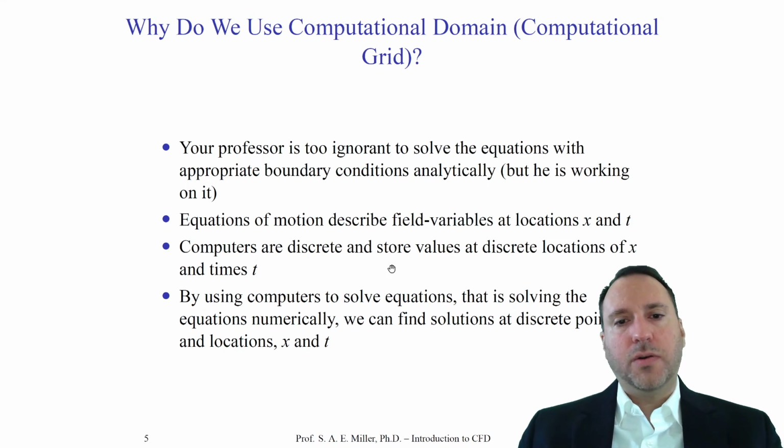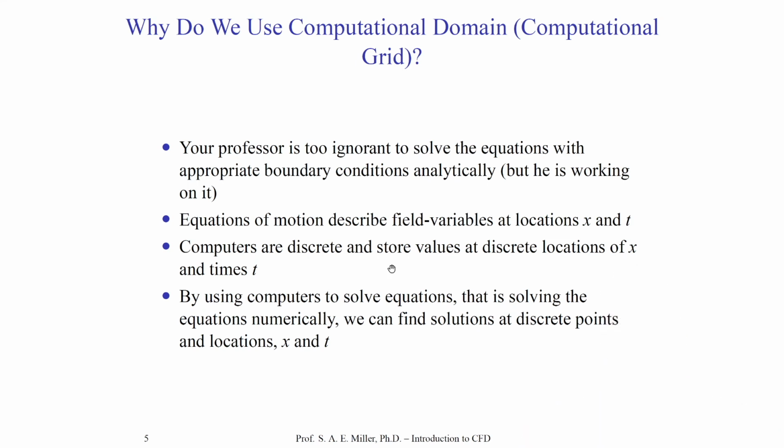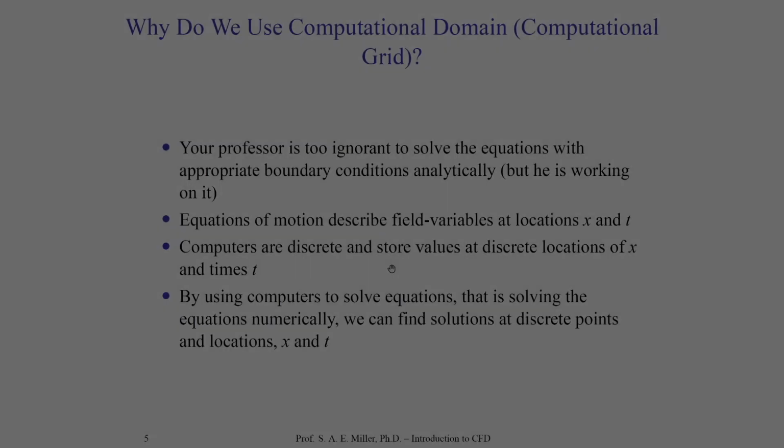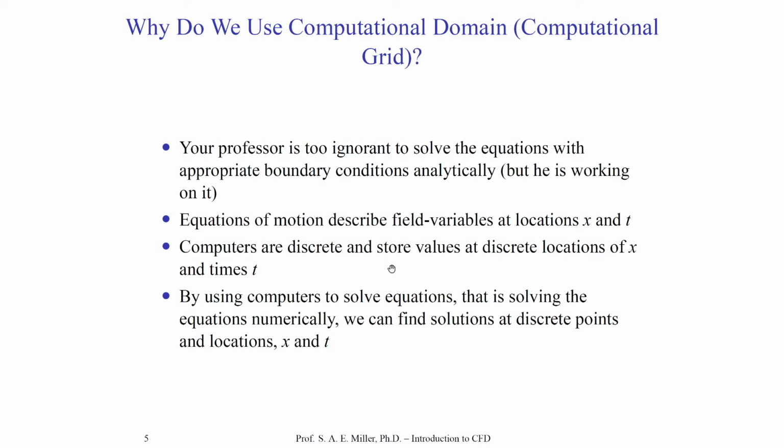This is the core reason why we are performing discretization. We are not solving the continuum form of the equations. We're only solving the discrete form. This is a critical concept that many students struggle with. The struggle for many new users of CFD is asking, unlike other fields, why we need to solve for the whole solution in the entire computational domain. Well, it's because we need to solve the equation everywhere for it to be valid within the whole domain. It's that simple.